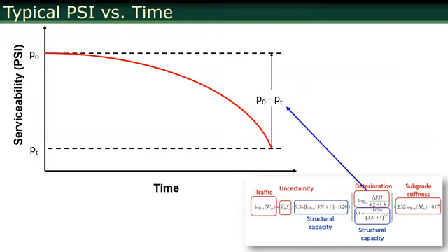Initial condition is zero cracking, let's say zero rutting, IRI at a certain level here. This is like your final distress threshold. The final distress threshold is increased and decreased depending on different factors, so that's what people usually do. So what should be the final serviceability?